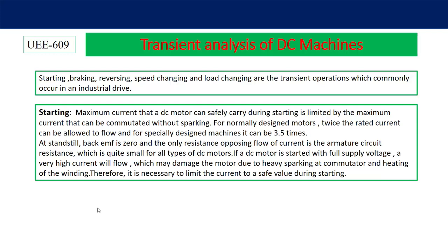or a suitable current limit controller is to be implemented in the circuit so that current should not exceed the rating of the motor winding. The maximum current should not develop any sparking in the system or across the commutator. Commutators are connected across this DC machine to ensure that current always flows in the same direction in the armature conductors at the time of rotation of the motor.